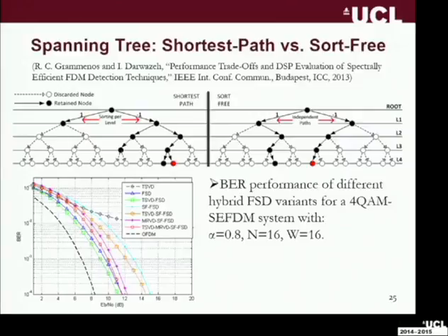What if we get rid of the sorting stage? If we just remove the sorting stage completely and we just say, we'll pick the 50 at that point and then the 50 at the other point, and basically you're creating independent paths. Again, same trade-off. You get a simplified algorithm that works faster, but at the expense of degraded bit error rate.